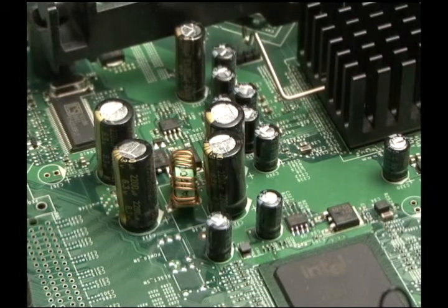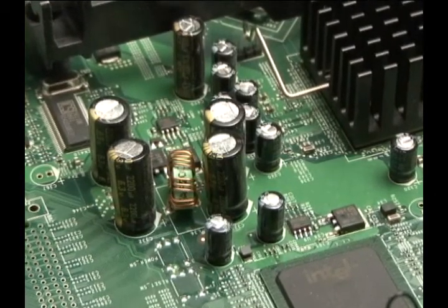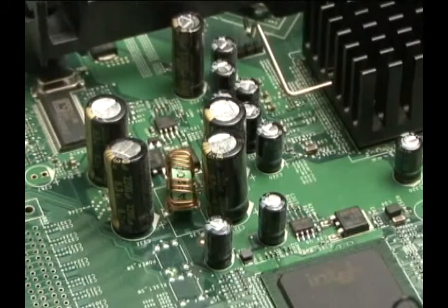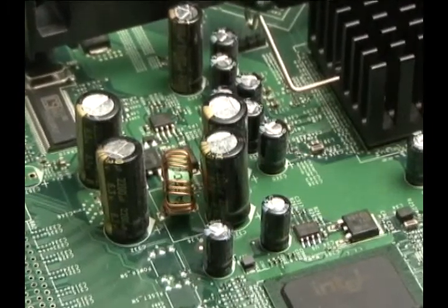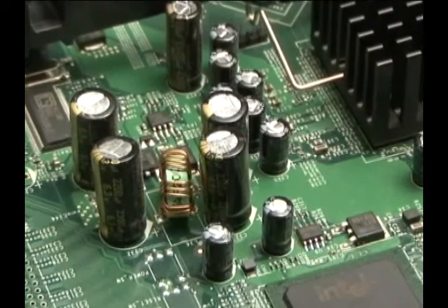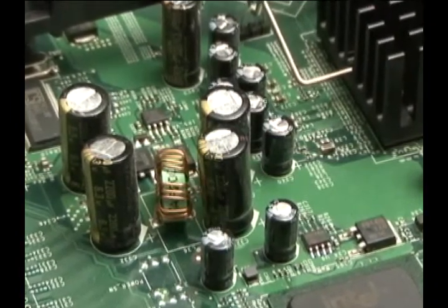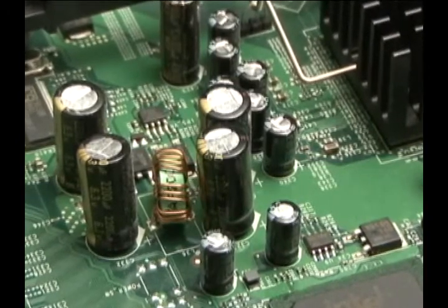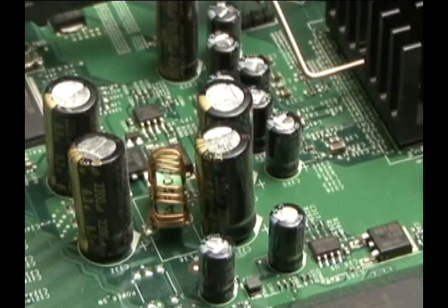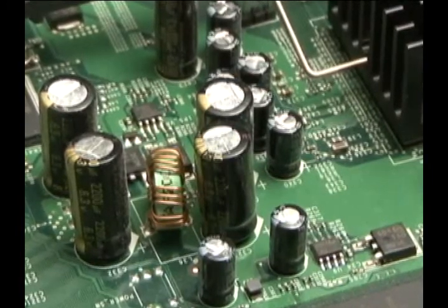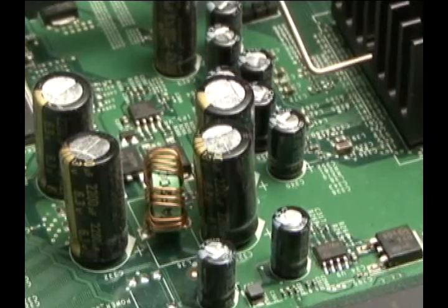Aluminium electrolytic capacitors offer high capacitance at a low price, leading to their frequent use for applications wherein the voltage of the electrical circuit board must be kept constant. Compared to other capacitors, however, they have a relatively short useful life, about 7 to 8 years on average. This does not mean that they cannot be used after 7 or 8 years. It means that electronic devices that use aluminium electrolytic capacitors may begin to generate heat or emit noise as they age.